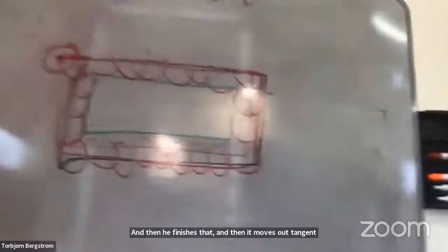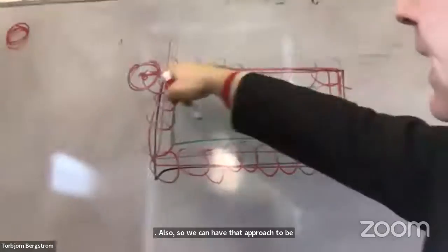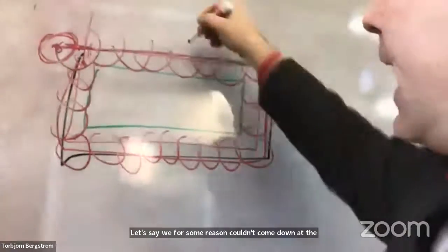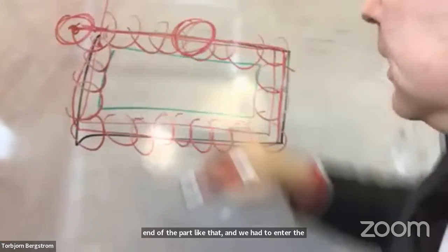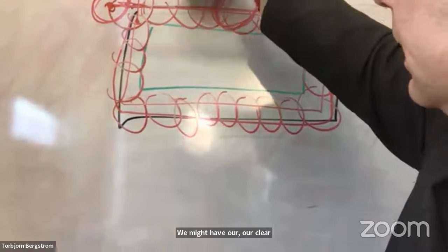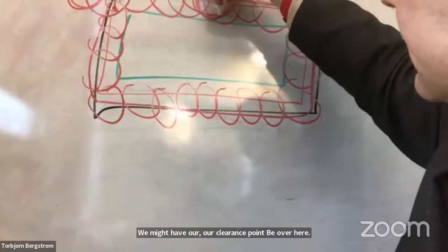So we could have that approach be tangent. Let's say we, for some reason, couldn't come down at the end of the part like that, and we had to enter the cut at this location. We might have our clearance point be over here, and then we'll come in on a radius to the part.